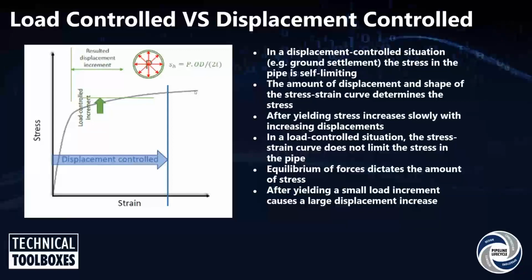Before yielding takes place, there is not much difference between load control versus displacement control. But after yielding takes place, generally speaking, pipelines are less sensitive to displacement control conditions. So displacement control condition is more desirable. Examples would be differential temperature or ground movement.